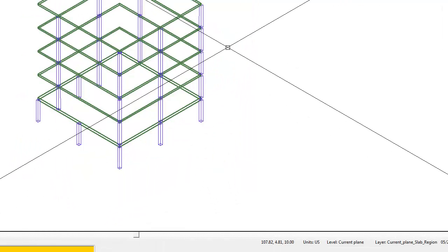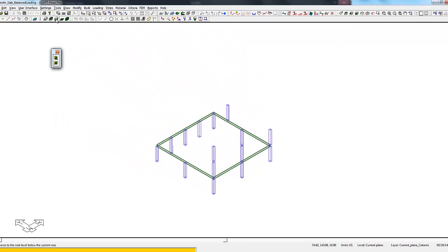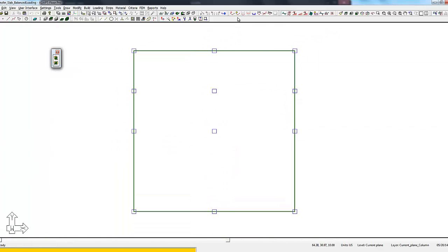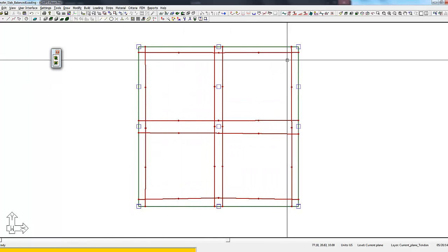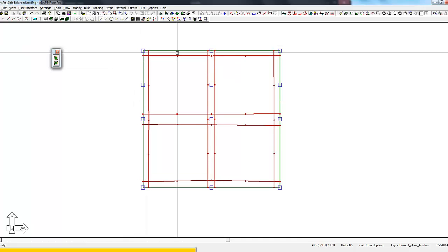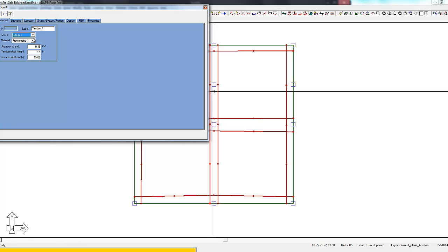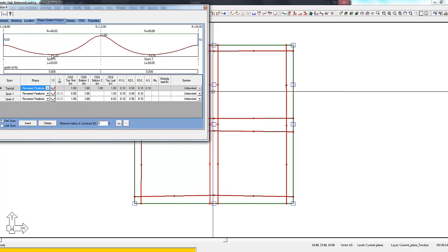So to begin, we're going to go down to that specific level using the Story Manager toolbar. And if I open the tendon display view, we can see we have some tendons here. So we have tendons basically on each of the grid lines. We have 15 times 2 grouping, so we have a total of 30 strands here where we have the transfer condition.